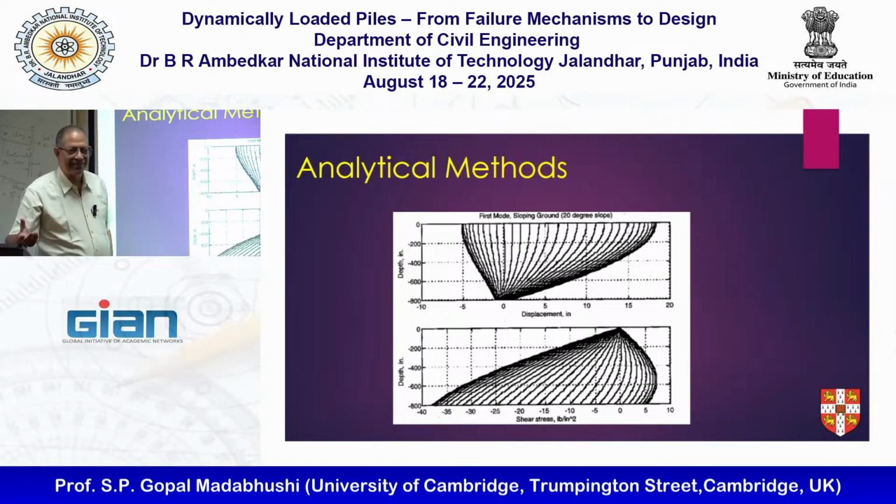Pound is a force, obviously, but pound is also weight. So obviously what they mean here is pound force per square inch. We can sit down and convert all this into kPa quite easily. So 1 pound is 2.2 kilos, so it's about 22 newtons, and an inch is 25.4 millimeters. Convert that into meters, and you can convert that into kPa with a factor.